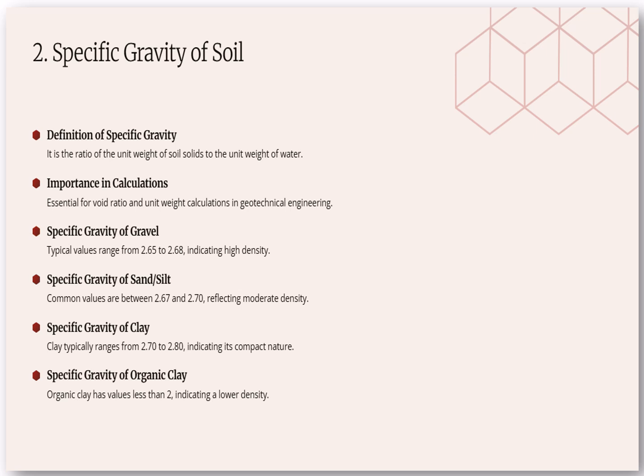The second index property is the specific gravity. First, the definition: it is the ratio of the unit weight of soil to the unit weight of water. What is the importance in calculation? This is essential for void ratio and unit weight calculation in geotechnical engineering.